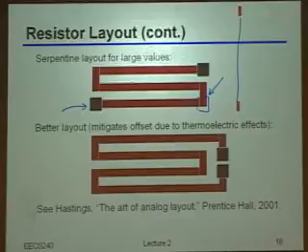It turns out there's actually even more interesting effects you can get into, where, in particular, if you're using poly or diffusion-based resistors, it turns out they're actually thermoelectrics. So if there's even a temperature gradient that resistor experiences, you'd see errors in matching, or in fact it might even act as a thermoelectric generator. Okay? So there are some more clever layouts you can come up with based on this kind of snaked thing, symmetrically around the center point, that would cancel some of those effects.